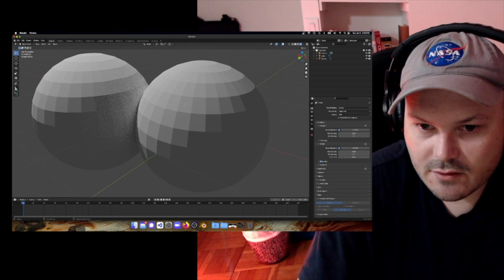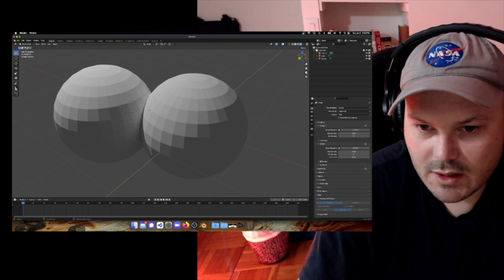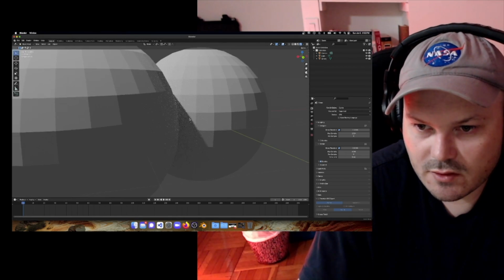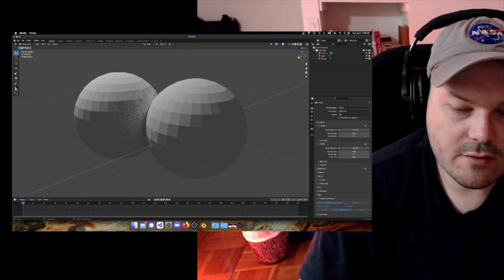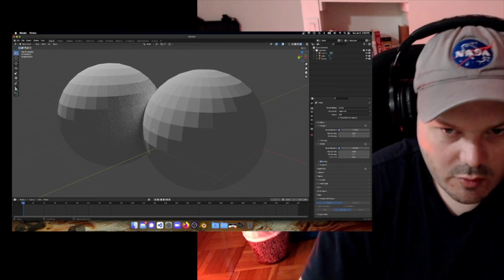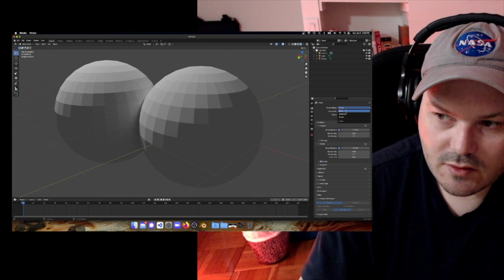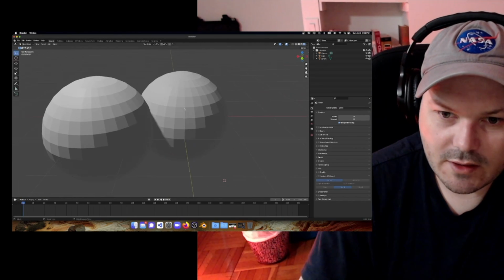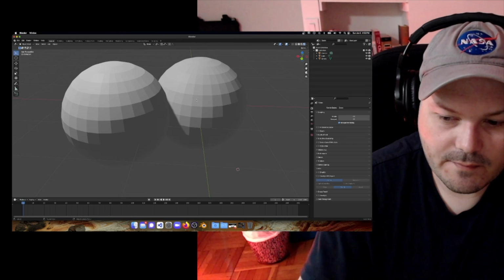If I go to Cycles, Cycles shows bounced secondary light, and the shadows are much more defined and smooth. So just know that. I do a lot of photorealistic or hyper-realistic rendering, and for that I use Cycles. But Eevee is quite popular because you can work in Eevee and kind of estimate how the scene may look later.